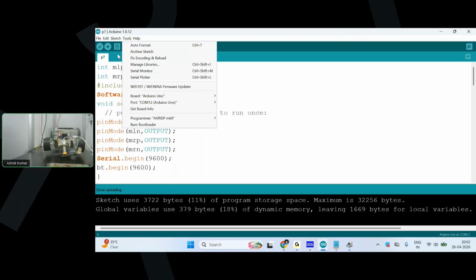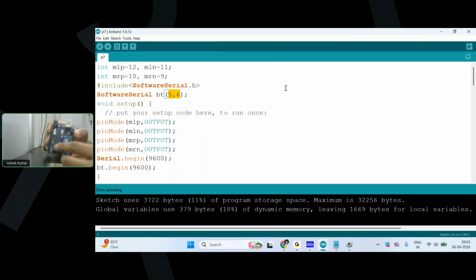So that time your Uno board understands that it has to transfer the code from Uno itself to the Mini board because the pins 0 and 1 are engaged. And that time because Mini is a programmable device, it uploads the code easily. There you won't face any error. But here we have one more condition. In your board, when you are connecting it to program the Mini, you need to remove this IC. This is a DIP board, so you can easily remove this IC from the base, right? If you purchase the SMD board, you cannot remove the IC.